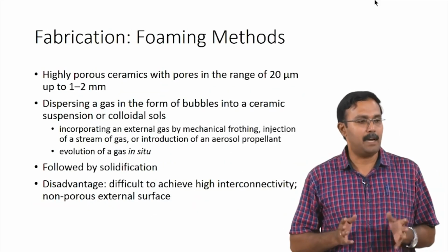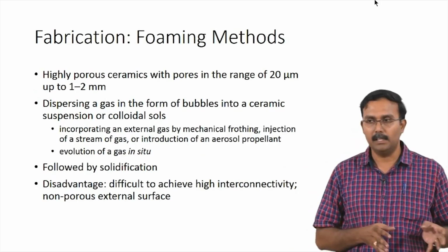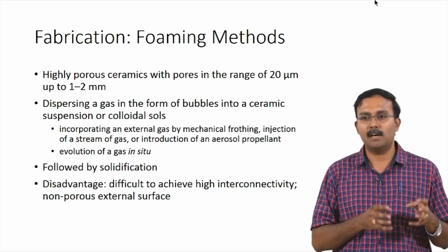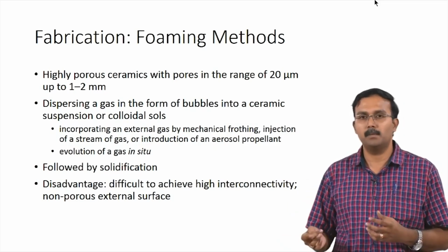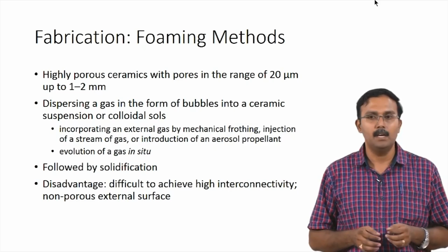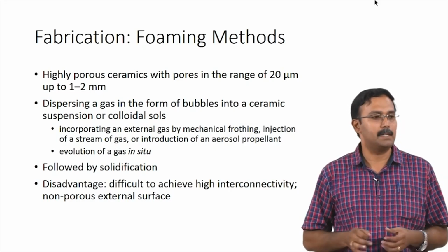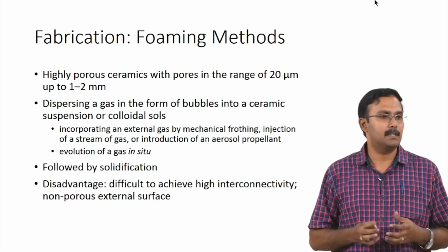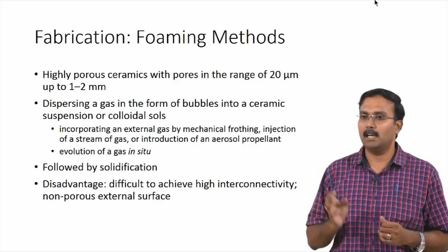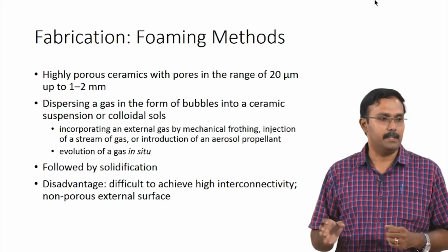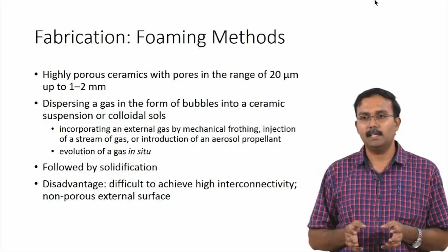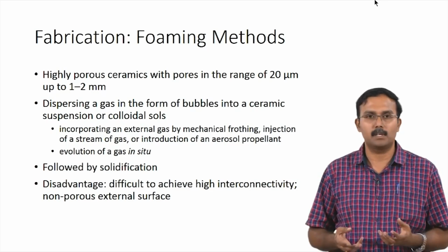We looked at different fabrication techniques for scaffolds earlier. The techniques which we looked at were all primarily for polymers, right. Those are scaffolds which we can prepare from different types of polymers. Similarly for ceramics, there are different techniques which can be employed, and we will just quickly go through some of them. One of the most common techniques is the foaming method. Porosity is crucial for ceramics because that is what will regulate osteoconductivity. Bone ingrowth will happen when you have a porous structure. So, the techniques which we will be looking at have the ability to create these porous structures.